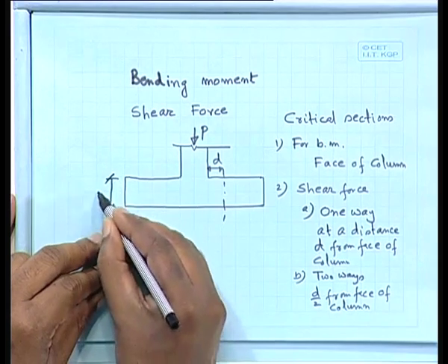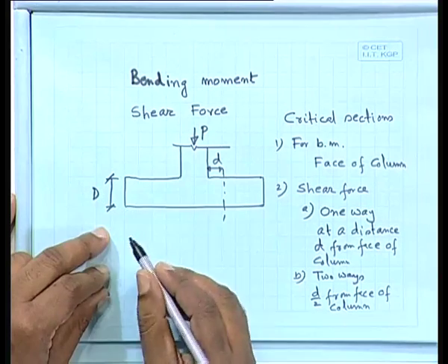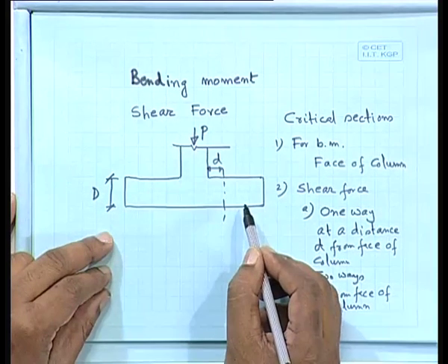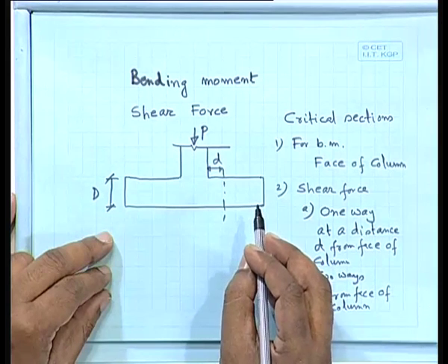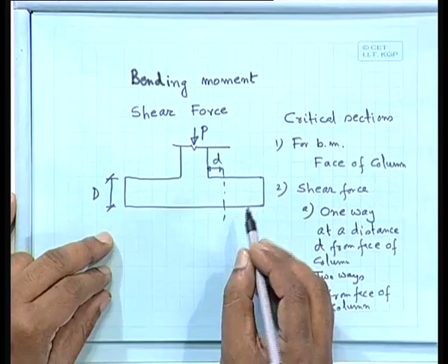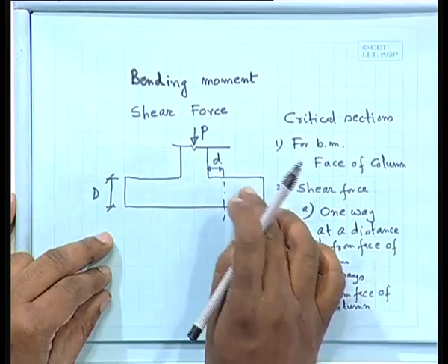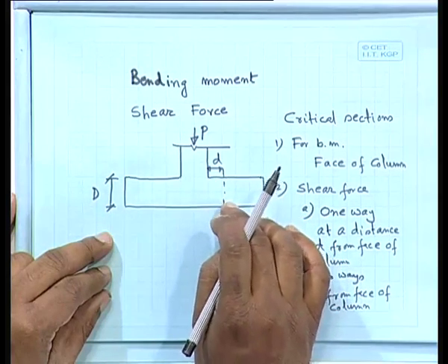This depth of the footing you have to provide, that is the first thing, the overall depth. 50 millimeter we have to provide as the clear cover, that you should remember. Then we have to provide reinforcement. For this type of thing, you can consider this one as a slab.